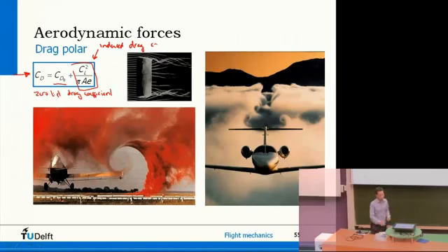So there are some additional parameters, but you can see it's a function of CL squared and some other ones, pi, A, and E. Now pi, of course you know. A is basically the aspect ratio of the wing. So that's a constant factor. It's just a geometrical thing telling you how large is the surface area of the wing and how wide it is.